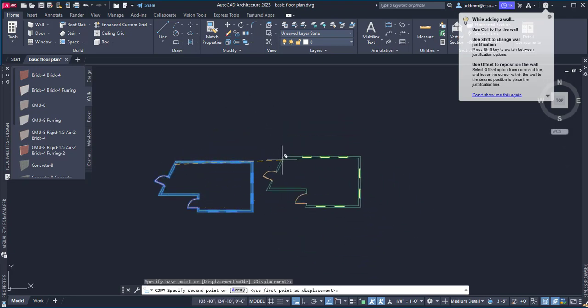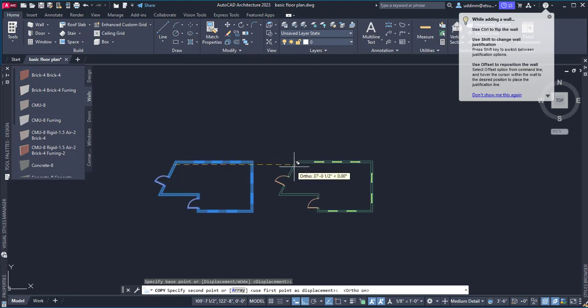Notice the ability to move this plan all over. Well, we don't want this to happen here. So what we want to do is move this plan directly to the right in this case. So we want to toggle orthogonal on. We talked earlier about the function keys. So if you select function key F8, that will allow you to just slide it right to the right.